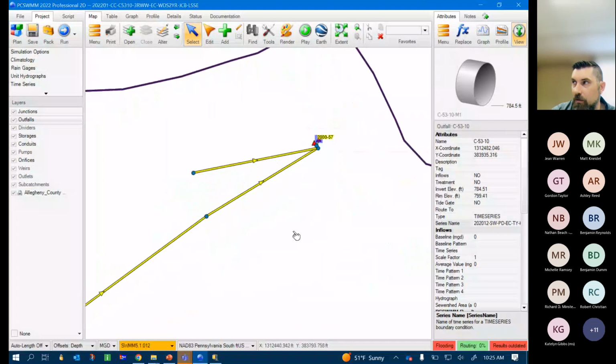So our river boundary conditions are staying the same. You may only have 1, 2, maybe 3 or so locations you need to change. It's going to be a head boundary condition at the downstream end of your submodel where it goes into an interceptor, or into a trunk line. And you may have upstream flow boundary conditions that would need to change. This particular one doesn't have that, so.